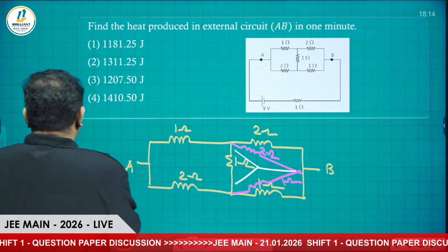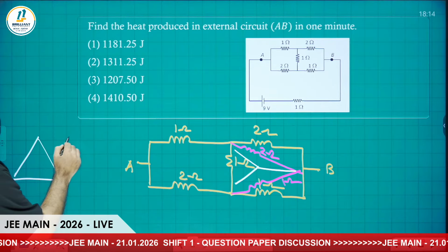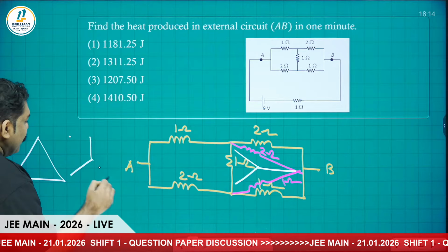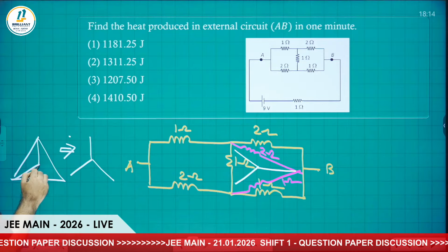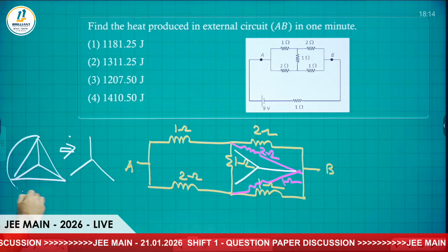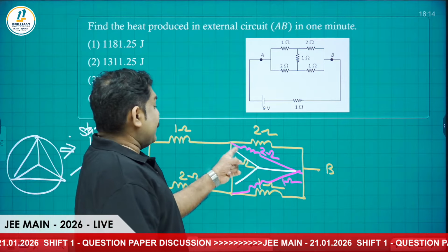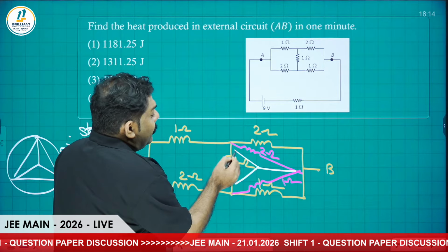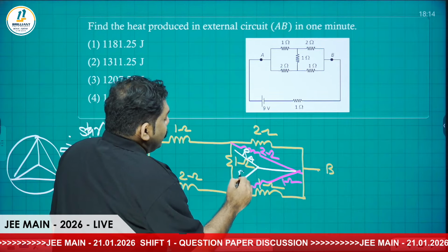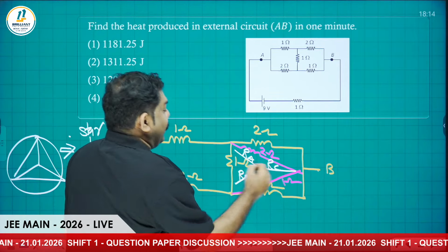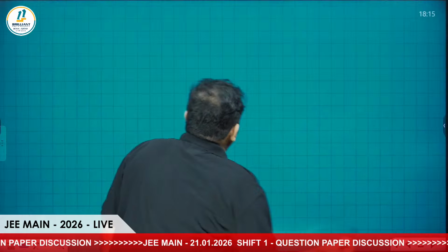So look, what is the picture here? What is the star delta conversion? If this is delta, you can convert that into this format. This is the star delta conversion that we explained in classroom. So this delta I'm going to convert into star here. Now there are these resistors. How can I calculate this resistance? Suppose I am marking this as RA, these as RB and these as RC. For conversion we studied how we can calculate RA, RB and RC values.